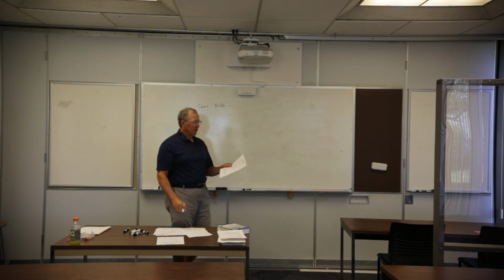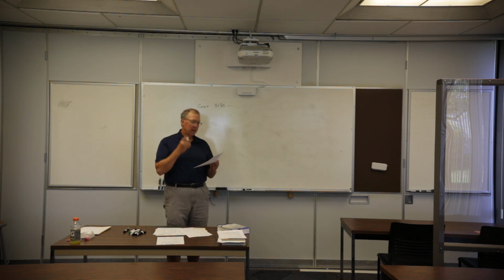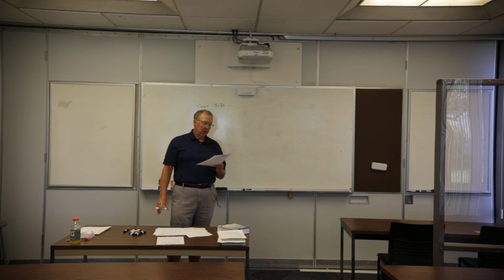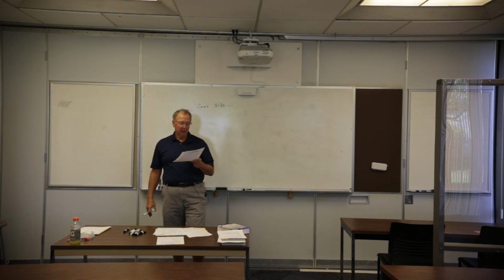Okay, we talked about SLO, Student Learning Outcomes. That's a function of the accreditation team, ACCE. So that's not really what you're worried about. Course objectives are you've got to be able to use a tape and make associated corrections and do layout. You ought to be able to do leveling, vertical control. You'll be able to use the level, the laser level, set them up, and tie them to a rod of some sort.